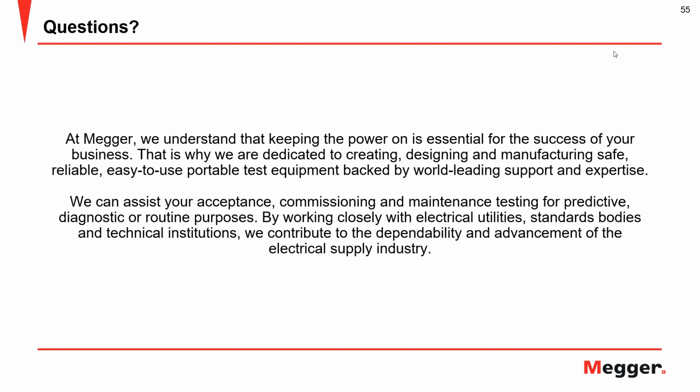Maybe I can just add one thing to it. These factory tests, according to IEEE also, for accessories and for the cable in the cable plant or the accessory factories, follow IEC 60270. But in order to address this issue of the background noise that Robert was talking about, they do it in a Faraday cage. All the measurements are done in a Faraday cage. So if we could do a field measurement in a Faraday cage, then we wouldn't have this background problem, and we could see these PD levels that you see in a factory.